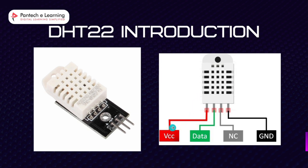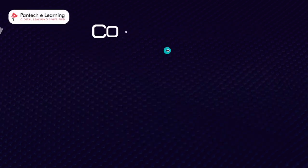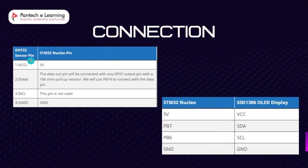VCC is the power supply pin, and data pin is the digital output pin. It sends out the value of measured temperature and humidity in the form of serial data, and NC is nothing but not connected, okay, and then the ground pin. So here I provide the connection details: DHT sensor with Nucleo pin, power pin, data pin and the ground pin. So this is the not connected pin, you can leave it. If you buy this sensor in module format, you will not have this not connected pin, it will only have 3 pins, okay.